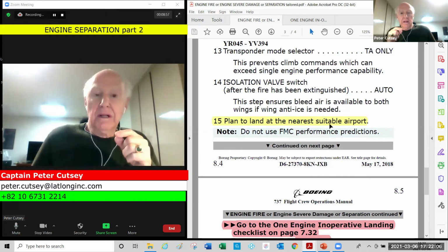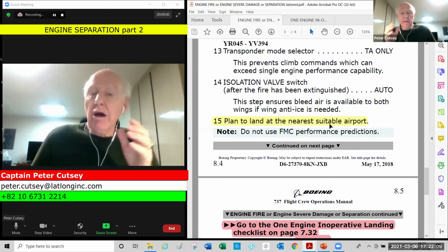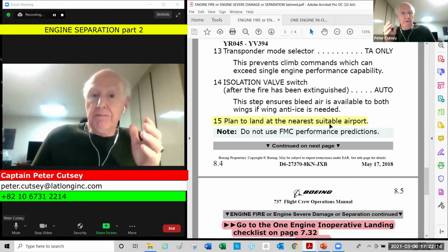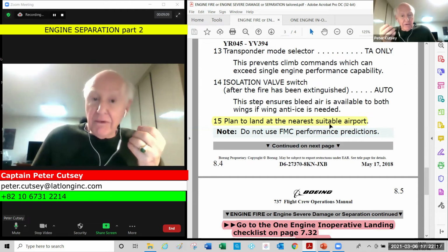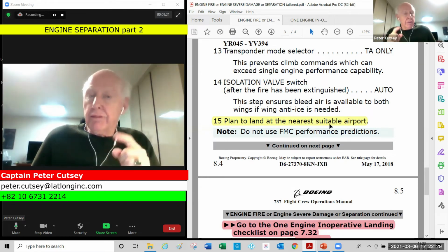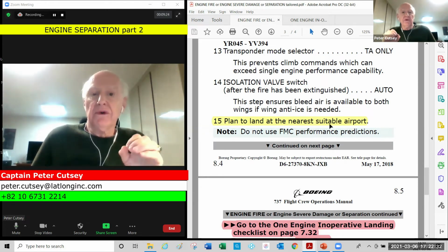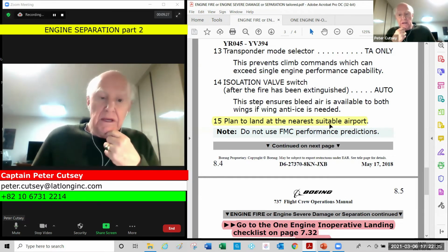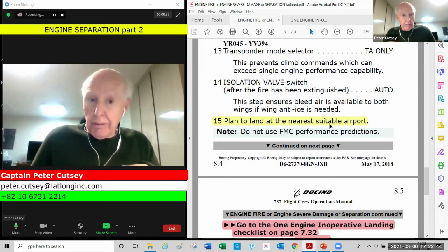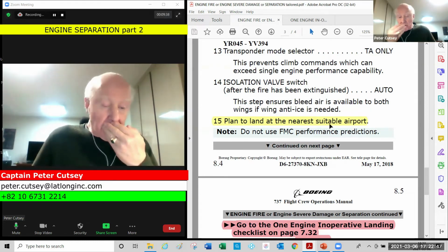And that's important. You've got a fix page. You may not be ETOPS, but if you think that every flight is really ETOPS, then your thinking and professionalism is of a high standard. You've got a fix page. Put on the airports that you know along the route that actually are good airports, not just adequate, but suitable if you did have to land en route. So this is all part of airmanship thinking you should be using. And remember that fix page that has a 511 nautical mile circle radius. Excuse me.